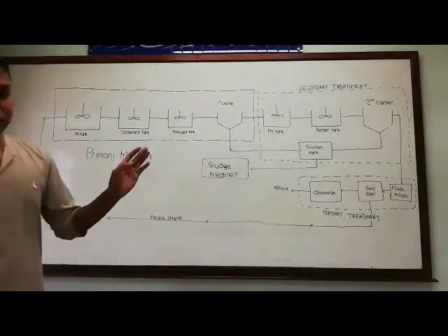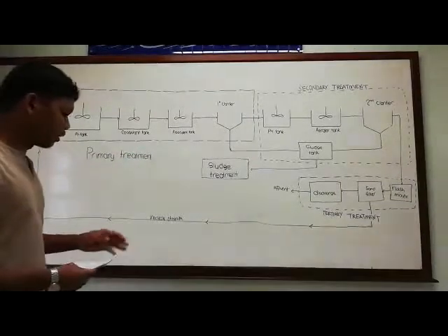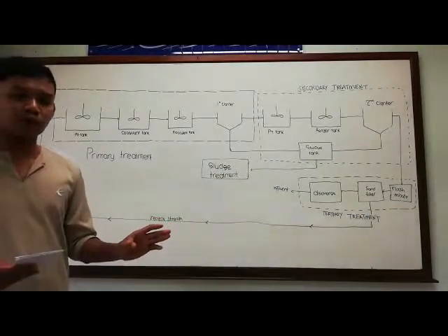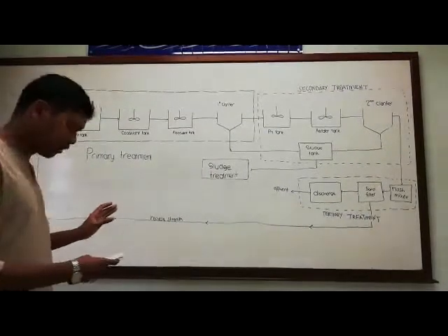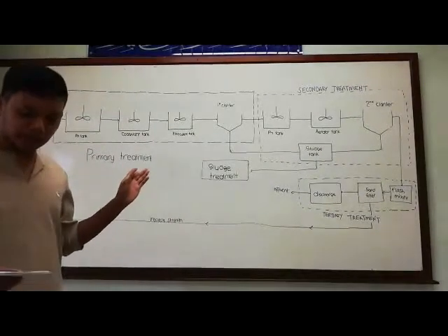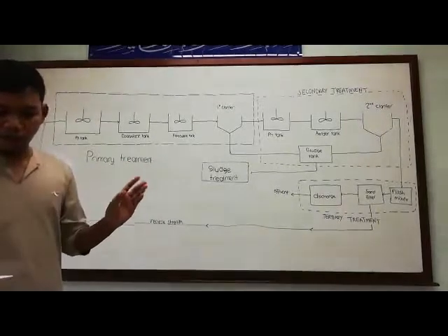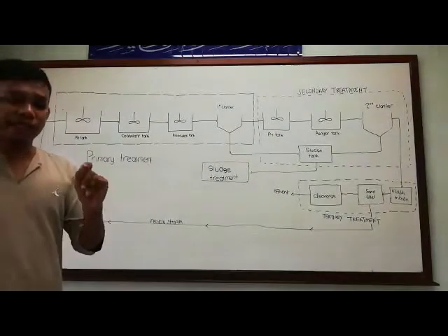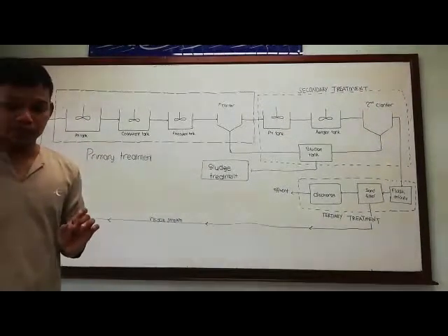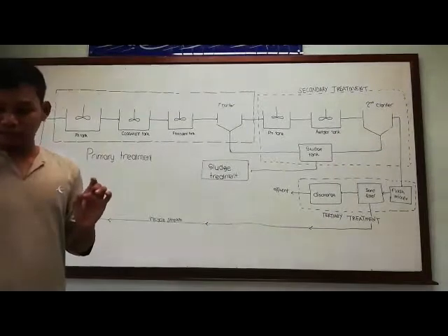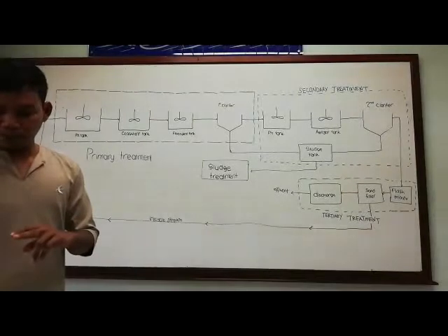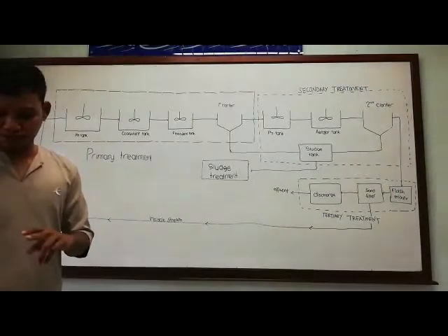And we proceed to the next section, which is the coagulant tank. For me, the coagulant tank is one of the important steps in primary treatment, where alum will usually be added in the process, which is a chemical compound that exhibits cationic properties. These cationic properties will attract dissolved solids and create neutral charge particles. These particles then stick together, producing large particles.